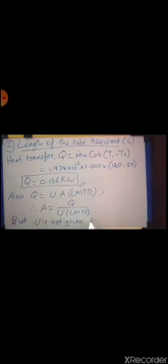But U is not given, but HI and HO are given. The equation for overall heat transfer coefficient U is, we know that, U is equal to HI into HO divided by HI plus HO.